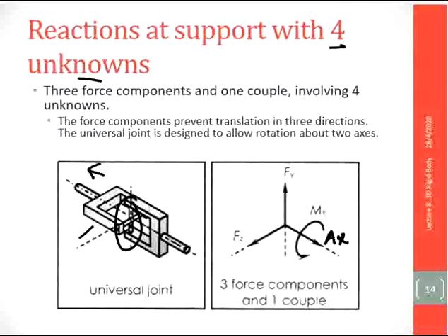It also cannot move in the z direction, so there is a reaction in the z direction, and it also cannot move in the y direction, so there is a reaction in the y direction. But this joint can rotate like this based on this structure, so it can move clockwise and counterclockwise about the x-axis.